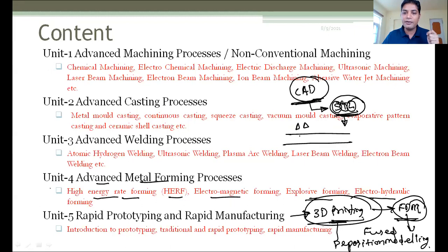If this is a line that we have to create, it will basically create these kinds of triangles on the particular line or particular surface. Then it is like slicing: one layer is done, then another layer, then a third layer, then a fourth layer, like this. So it's a slicing process. The 3D printer will read this STL format, so you have to convert using that software. Different software is available for different companies of 3D printers. We convert that, and then there will be 3D printing.